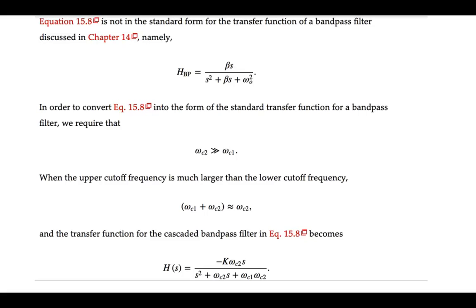The other issue is that, remember, the maximum gain you can have on a passive filter is equal to 1. On the active filter, we can set our gain based on either the input and feedback resistors of the high and low pass filters, or based on that third inverting amplifier that we set to be a gain not equal to 1. So this is your design equation for the passive RLC filter.